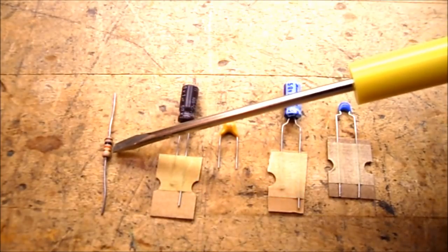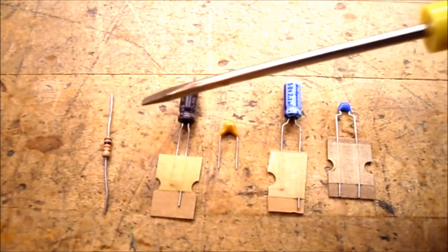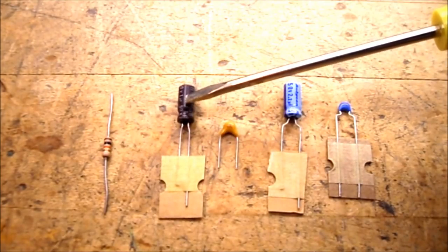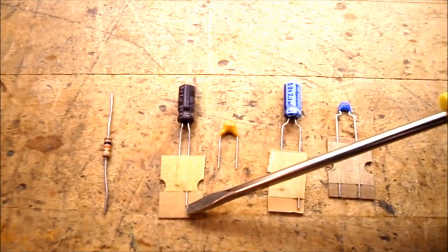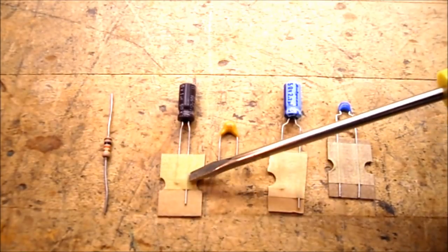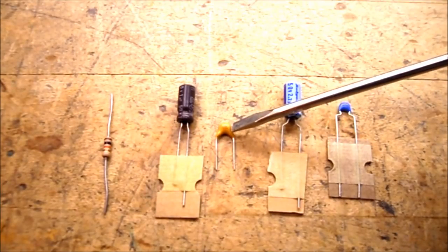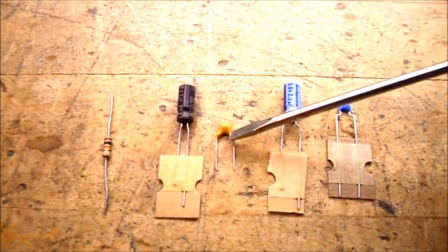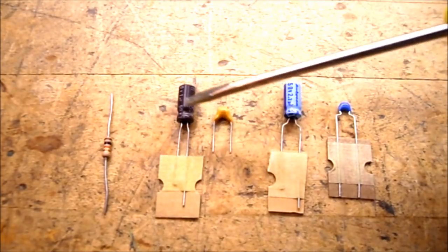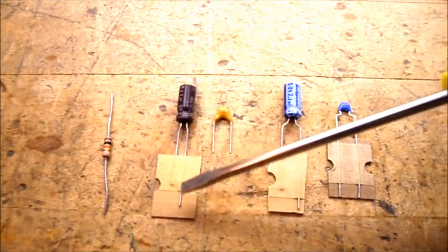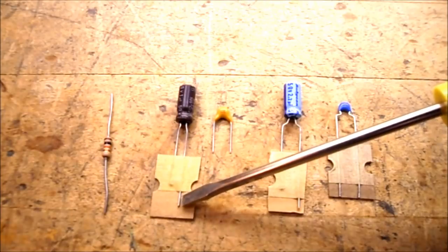This is the 10K ohm resistor. Over here I have an electrolytic capacitor, and it's 1 microfarad, and you notice one leg is longer than the other. So it has a positive leg, so you have to put these ones in the right way around. The capacitor beside it is labeled 105. So that's 10 with 5 zeros after it, picofarads. So that ends up being 1 microfarad. So both of these are 1 microfarad. It's just the one in the can has to have a positive leg, so it has to go in the right way around.